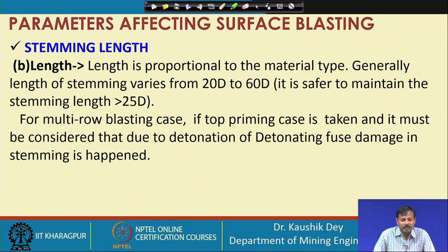Stemming length is in general proportional to the material type. Generally, the length of stemming varies from 20 d to 60 d. This is a thumb rule. When we design, we will see how it varies. It is safer to maintain the stemming length always greater than 25 d, which will reduce the chances of the